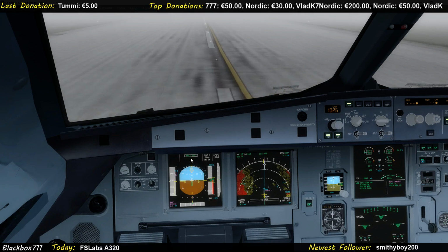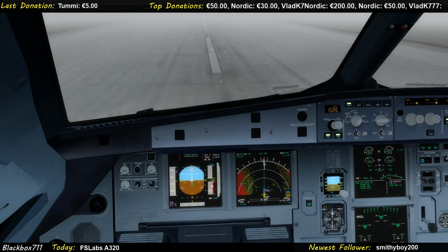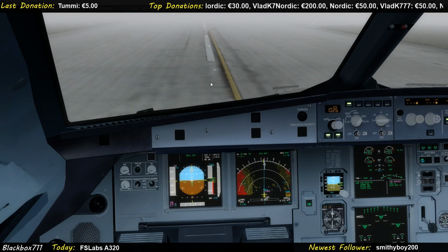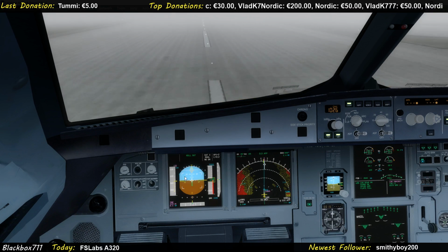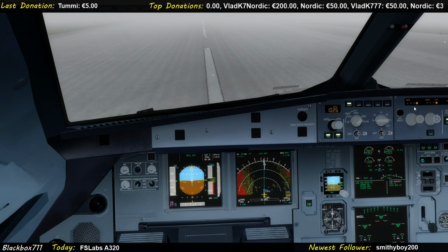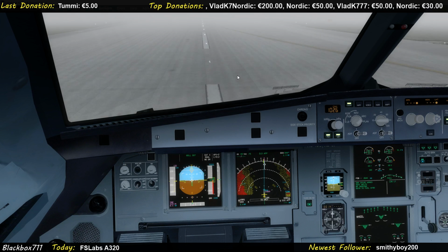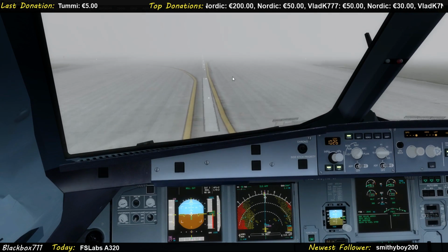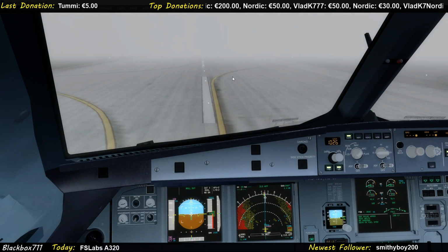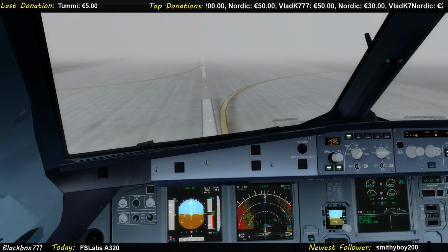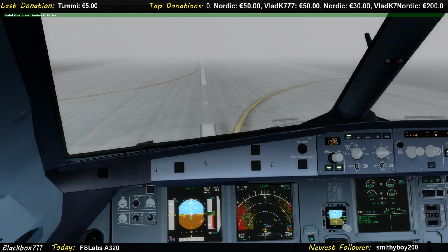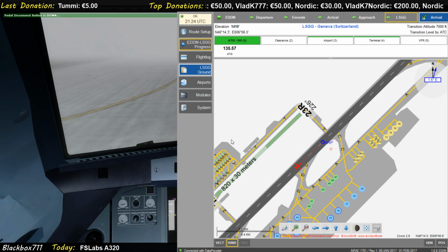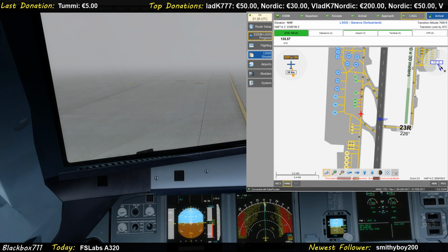And we have rollout, meaning the autopilot maintains the runway track according to the localizer. So idle reverse is enough, and right, manual brakes. Now we have to find an exit for us. Oh, here it is, and we'll take that exit here. And I can even show you where we are now. And we'll park there.